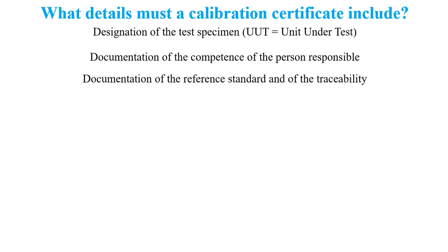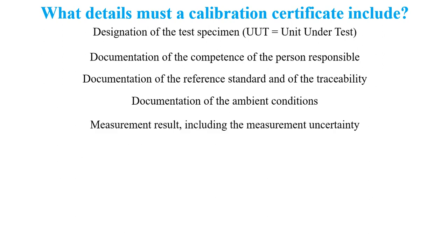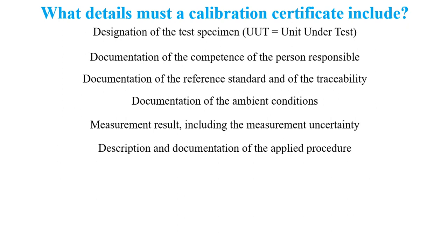Documentation of the reference standard and of the traceability. Documentation of the ambient conditions, and the measurement result, including the measurement uncertainty. Maybe we are talking about the variance. Description and documentation of the applied procedure. The date: calibrations must be repeated at regular intervals.